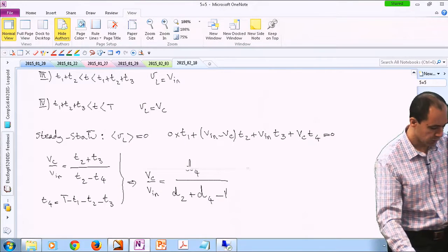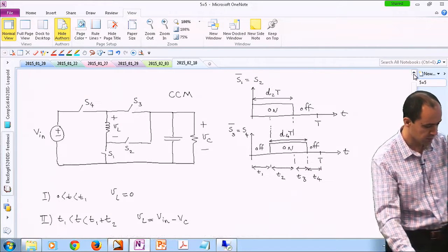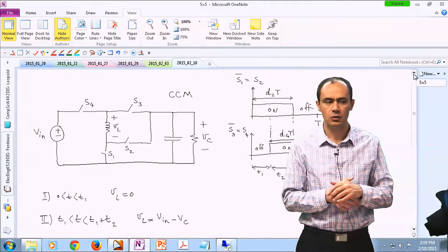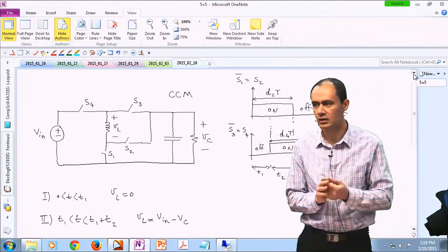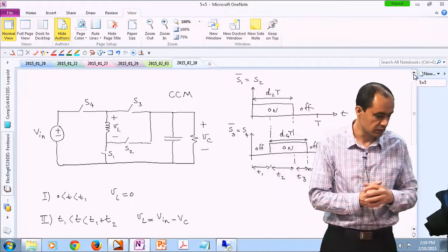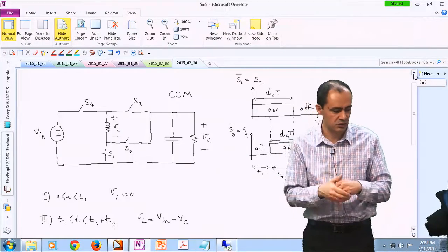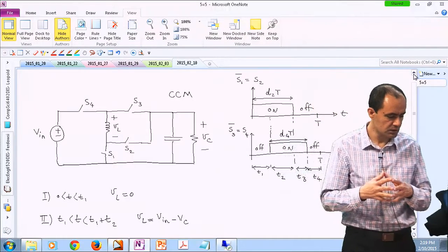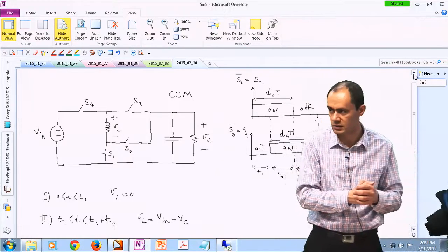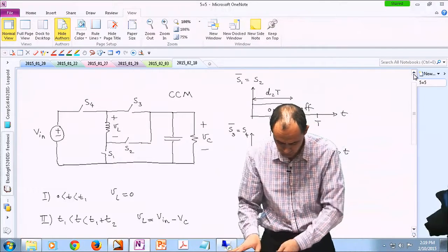So you may ask, okay, if creating this phase shift, which is labeled T1 over here, doesn't really change anything, why do we have to do it? We don't have to do it, but you may look at the pattern or the ripple of the inductor currents and realize that having this phase shift may help you normalize that ripple or make the peak-to-peak ripple a little bit smaller. So it's actually an extra degree of freedom. It doesn't change your output voltage, but may change some other components in the system. So it might be good to use.